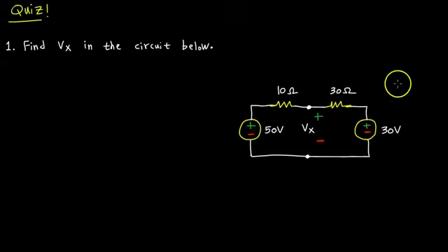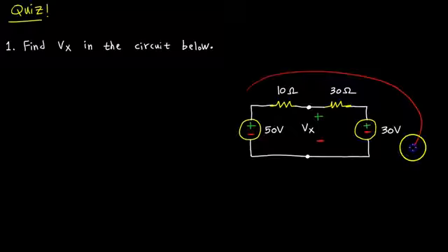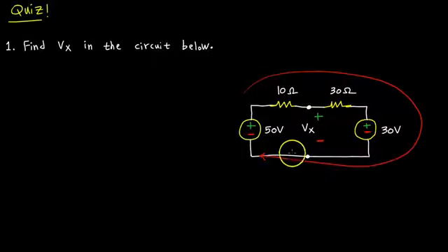So we're going to find the voltage Vx. I'm seeing one big loop in the circuit, so I'm going to use KVL, and since I don't have space to draw it here, I'm going to do it from the outside. So my direction is in this way, and I'm going to call the current I, lowercase I, and write KVL equation 1. I'm again going to start from the very bottom here, as I usually do, from the source, and go clockwise and see what I encounter.